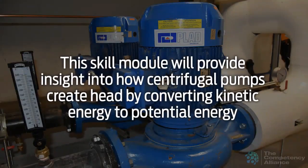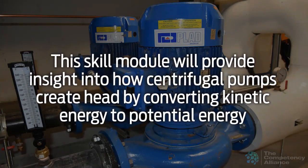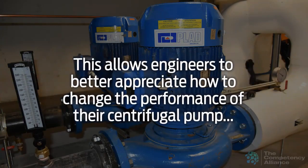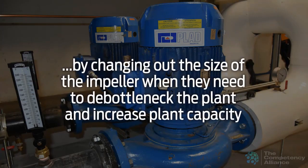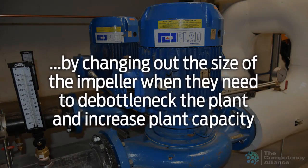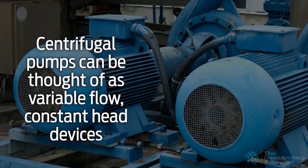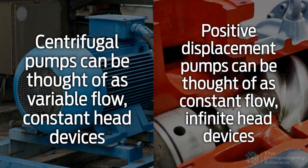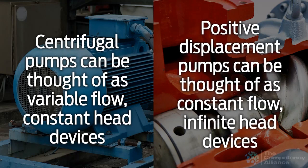In addition, this module will provide insight into how centrifugal pumps create head by converting kinetic energy to potential energy. This allows engineers to better appreciate how to change the performance of their centrifugal pump by changing out the size of the impeller when they need to debottleneck the plant and increase plant capacity. Centrifugal pumps can be thought of as variable flow, constant head devices. Positive displacement pumps, on the other hand, can be thought of as constant flow, fixed volume, infinite head devices.